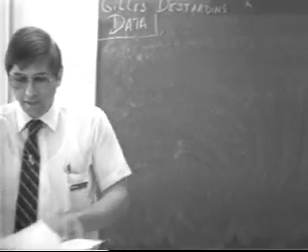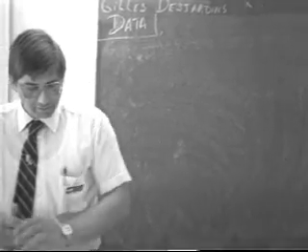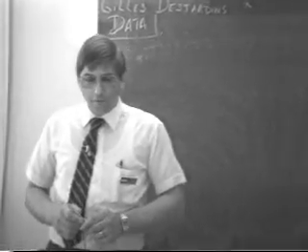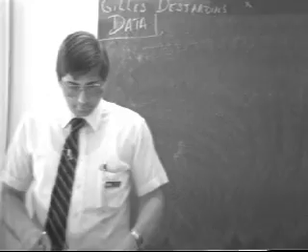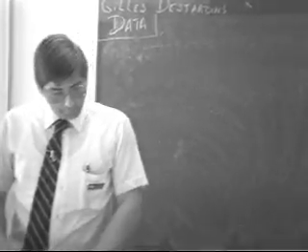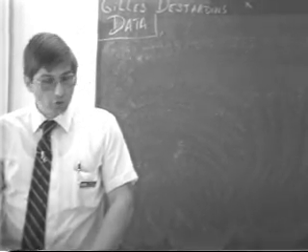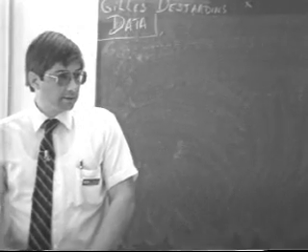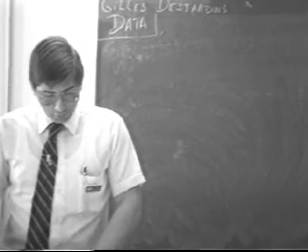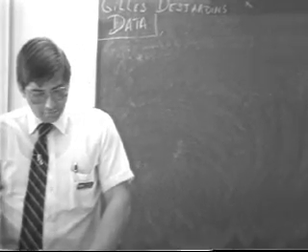Now on page 11, on its own, the C-bus interrupt. What happens when it sees an interrupt? It saves the accumulator, saves the local bus access status, wants to know where it was, what it was doing when it was interrupted, disables the local bus, enables the C-bus, reads the flag.